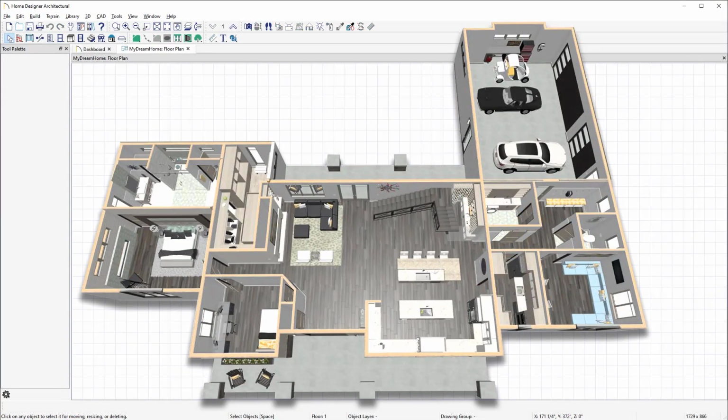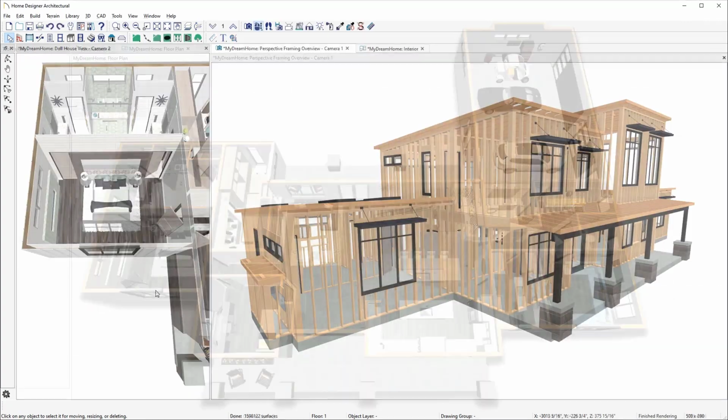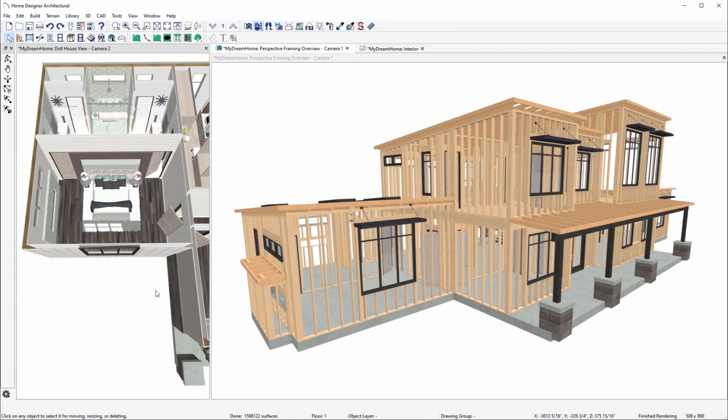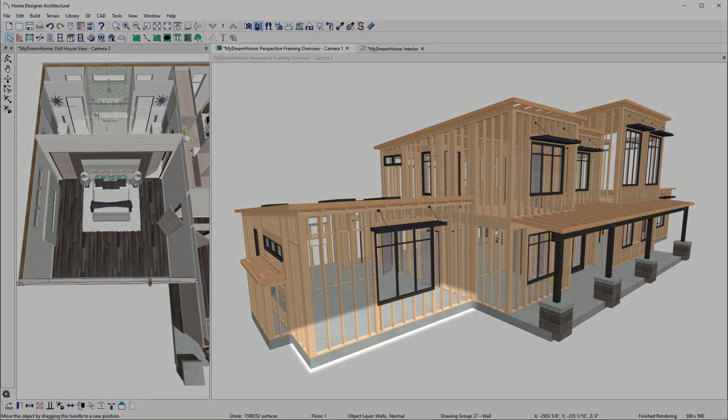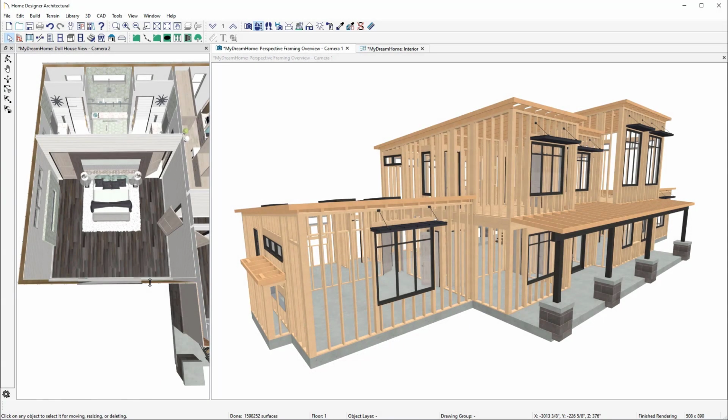With the interior completed, let's explore the program's automated building tools. Foundations, framing, and roof tools are automatically created as the design progresses. With these automatic tools, anytime a wall is moved on the main floor, the foundation will automatically update, and it will also update how much concrete and framing are required in the materials list.